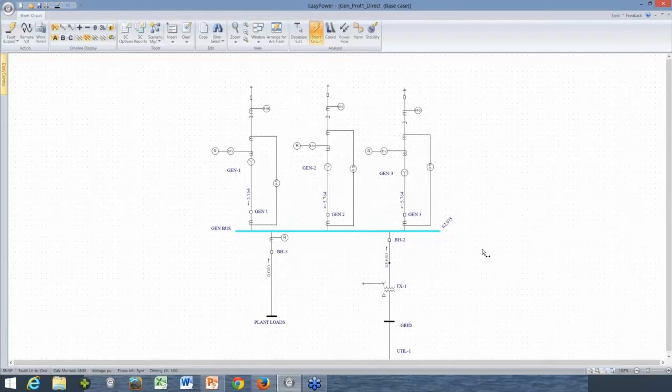And the phase current here is much greater. So if I were to have a ground fault within my generator, I'm going to have a huge amount of fault current flowing into that machine that's going to cause significant damage because this is solidly grounded. So to really protect your machines, you need to have every ground source resistance grounded.